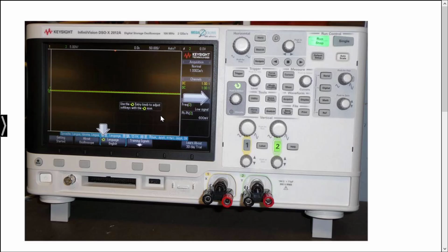So this is basically like a graph paper, and if you look closely, you'll see these little squares. It's like a graph paper. You can change how big or small those squares are. So on the horizontal scale, you will see time. So usually you will pick the time on the horizontal mode right here. By flipping this knob here, you can make those things bigger or smaller. And then we can measure two different waveforms, and these are called channel 1 and channel 2. And they have individual buttons to control the vertical spacing. So that's basically what it is.